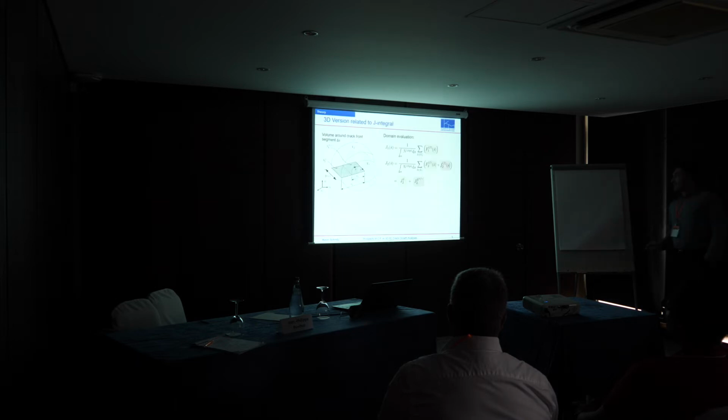To circumvent that, we first had a look at how the configuration force in a three-dimensional case is related to the vectorial J integral. We can see that the first component of J is only proportional to the configurational force that is the nice one, the volume contribution, indicated in green, but the value of J2, the second component of J, is related to both contributions.